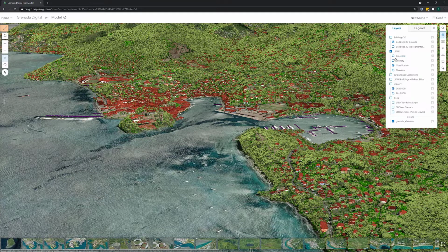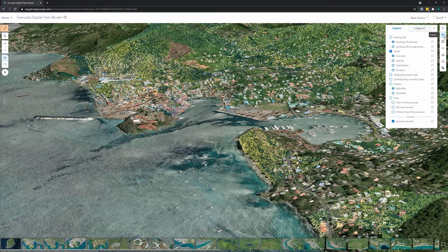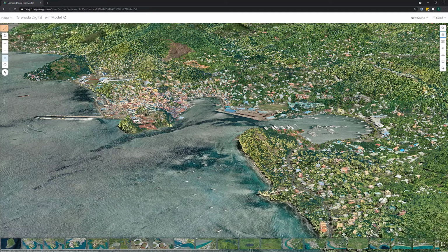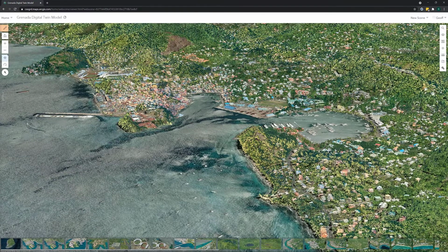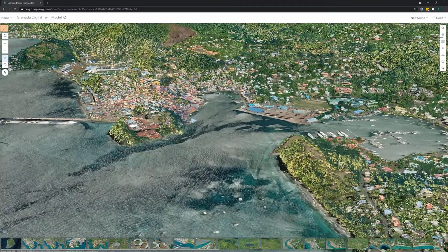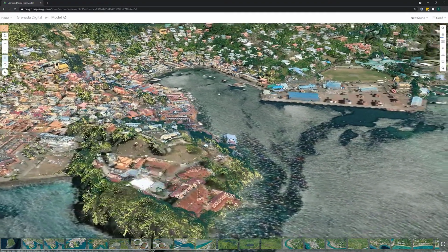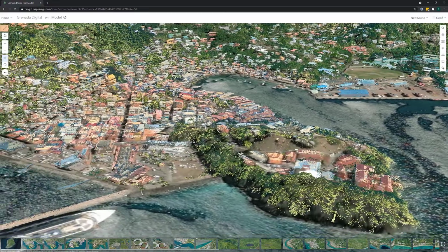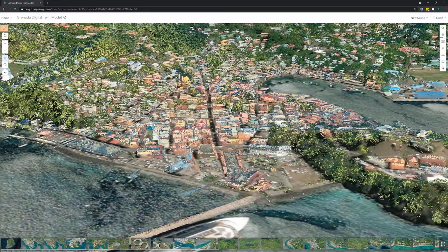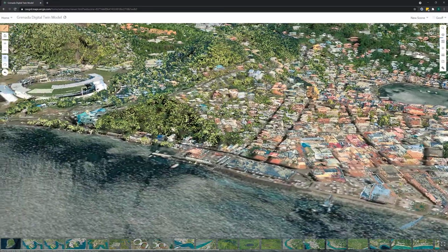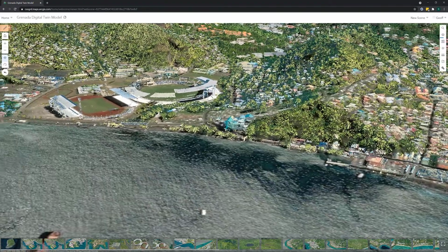In ArcGIS Pro, the LiDAR could also be colorized using ortho imagery for added realism, just as it was classified. And you can see how amazing the red, green, and blue values can be transferred directly to the point clouds for another iteration of your base map.